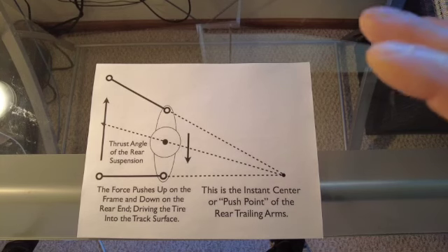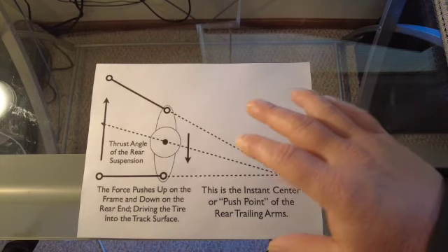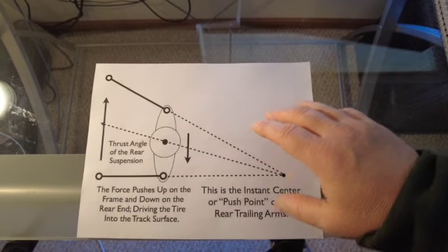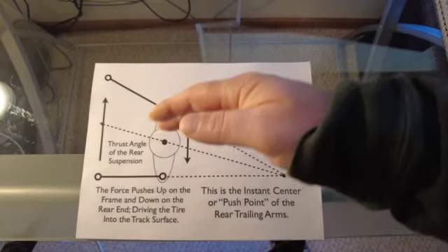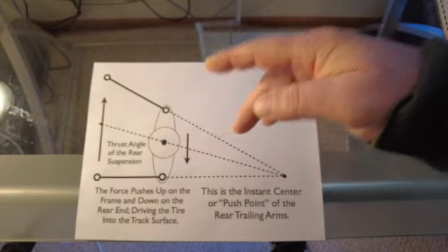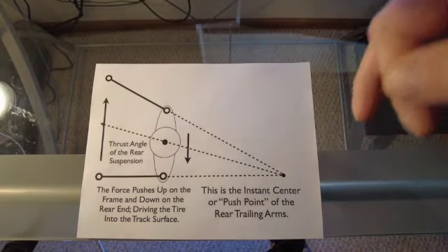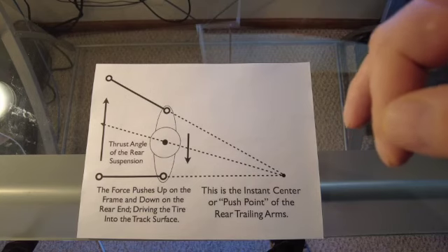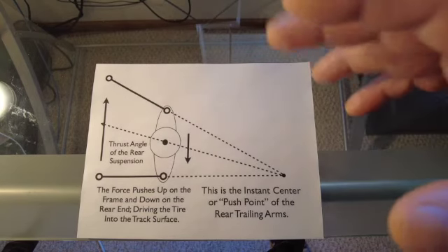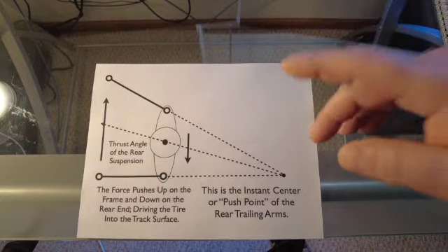Okay, here's the first scenario. Let's call this perfect ride height here. Your car rolls over onto the right rear and you get the correct dimension on your eye-to-eye on your right rear shock that Rocket recommends. That'll be a ride height.